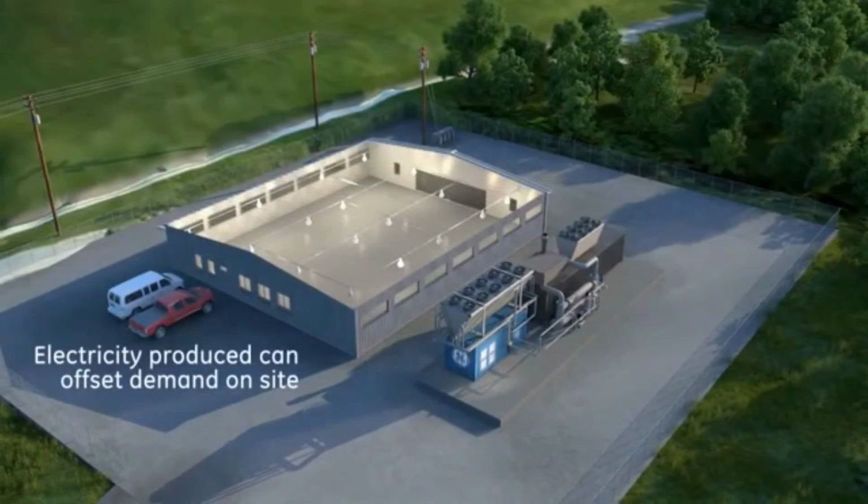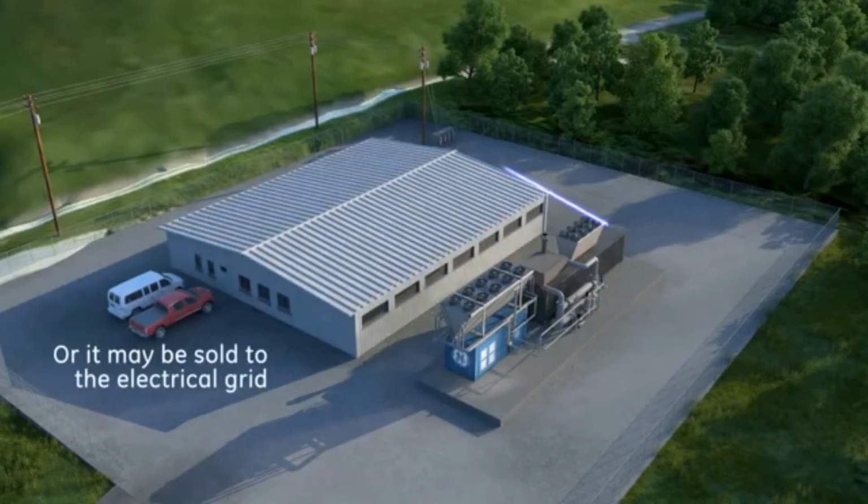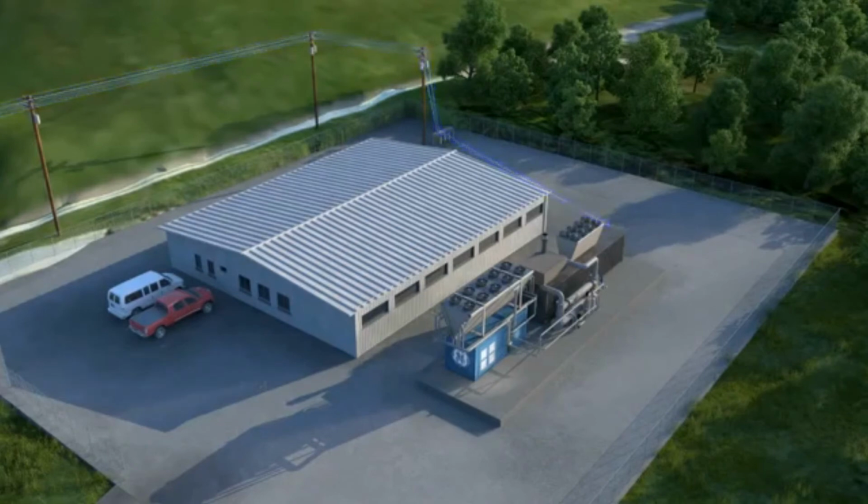The last main component from organic Rankine cycle is pump. The pump serves to pump the remaining vapor that has become liquid in the condenser to the evaporator or boiler with the help of outside effort. The liquid condensate leaving the condenser at stream 3 is pumped from the condenser into the higher pressure boiler. In the pump, there is no heat transfer occur, taking control volume around the pump and assuming no heat transfer with the surrounding. Mass and energy balance give Wp per m equal to h4 minus h3.